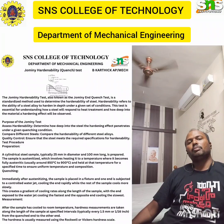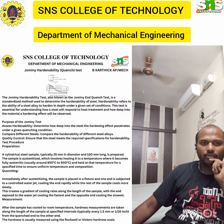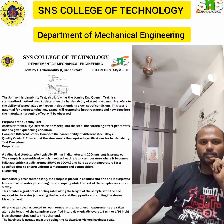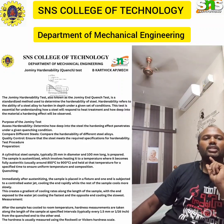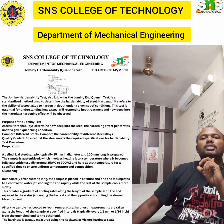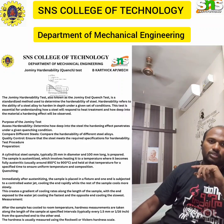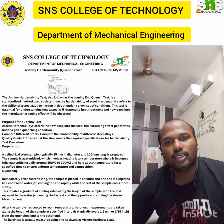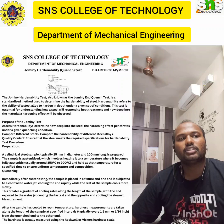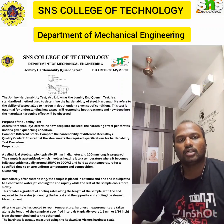Testing procedure, first one is preparation. A cylindrical steel sample, typically 25 mm in diameter and 100 mm long, is prepared. The sample is austenitized, which involves heating to a temperature where it becomes fully austenitic, usually around 850 degrees Celsius to 900 degrees Celsius, and held at that temperature for a specific time required to ensure uniform temperature and composition.